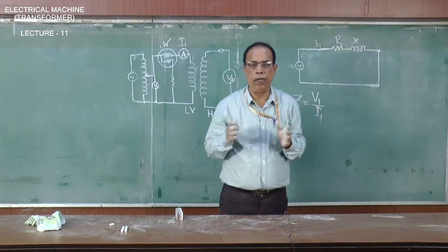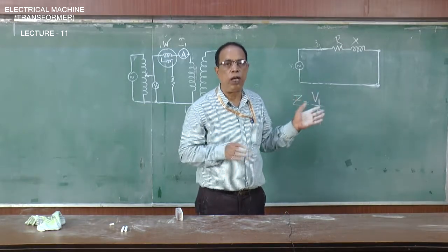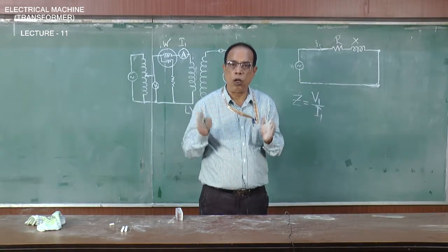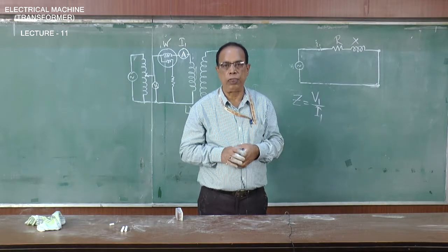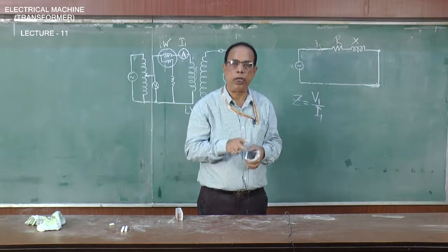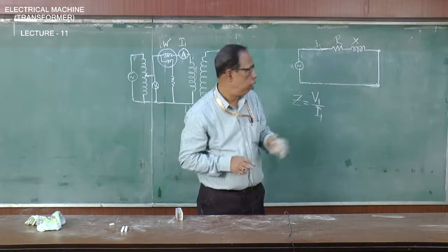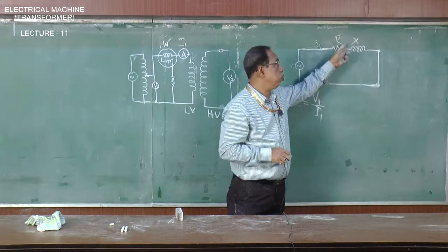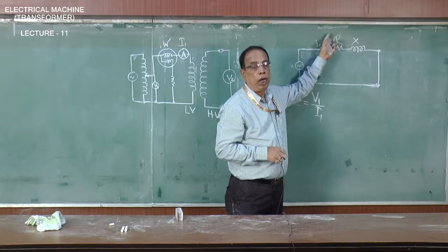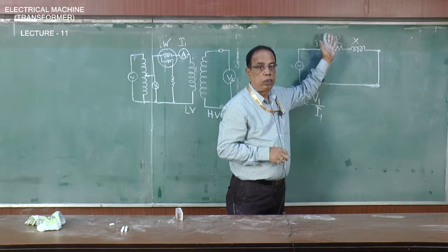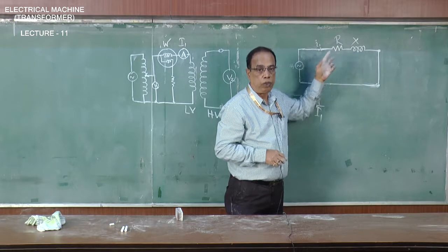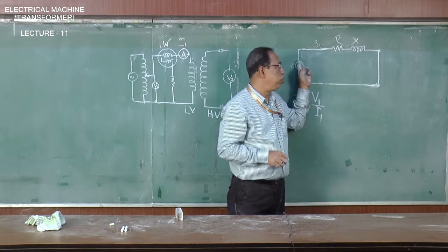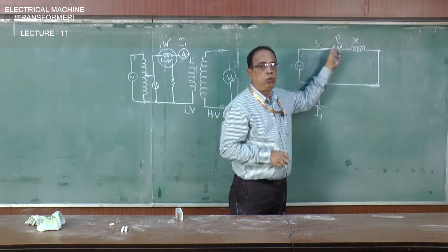That means, when full load current is flowing through the transformer, how the whole primary and secondary coil will behave, how much losses will be there, copper loss, that means loss which is caused by the passing of current through a resistance. Primary and secondary both have this resistance. So, this resistance will cause the full load losses, copper losses. So, that has to be accounted for. So, what we do is, by adjusting the voltage, we drive full load current through the circuit under short circuit condition.